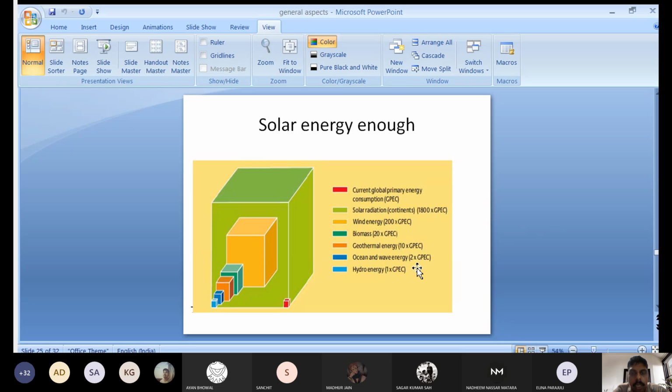But if you use solar energy in a device, this heat addition temperature is not there. 300 degrees Celsius will not be there. You can expect a maximum of 60 to 70 degrees without concentration. With concentration, you can have 100 plus degrees. 400, 500 is also possible, but with huge instruments, collectors and concentrators, which is not possible for a vehicle, combat vehicle, etc. So solar thermal we cannot use in vehicles.